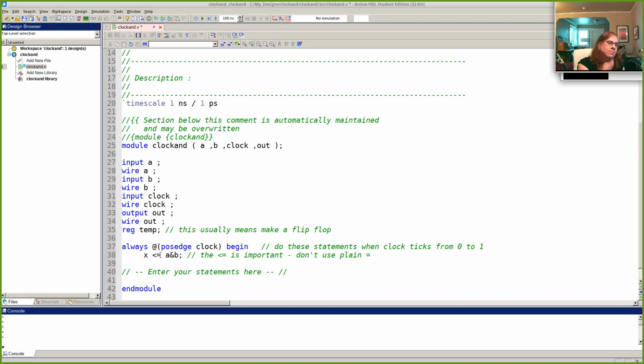Can you use a greater than equals? No, I don't think that's valid syntax. That would look like you were assigning something to the right if you did that, and I don't think it understands that. So that's really weird. Just think of it as one quirky double width symbol, like an arrow. And in some fonts it looks better, in some it looks worse. This one looks pretty weird. You got ligatures. Yeah. So that's just what we're going to use inside an always block.